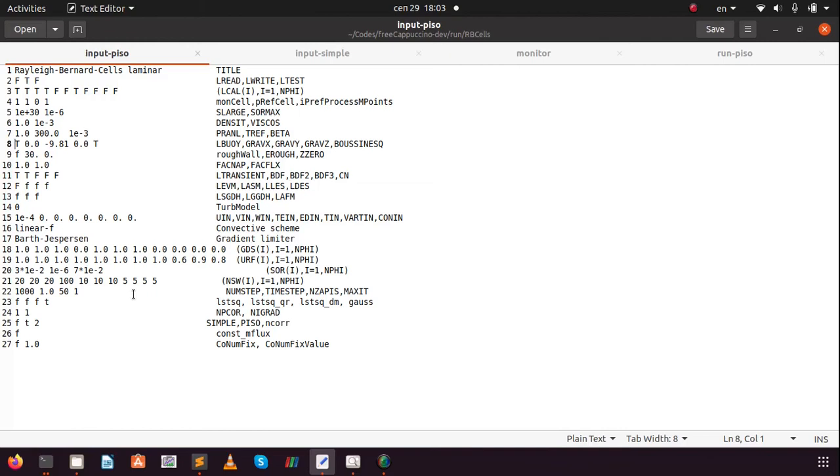Then we will form, assemble, and solve pressure instead of pressure correction equation, which is done in simple. But we will allow under relaxation of this field, and we will allow going back and performing some outer iterations. So they say it's a mix of simple and PISO algorithm. Of course, it is same here, but here we change it through parameter change. So we leave that it's PISO, but number of PISO corrections we set to 1.